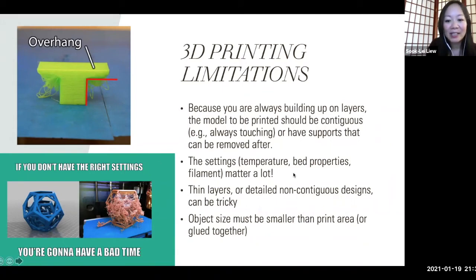And then the settings matter a lot. So we play around a lot of times with the temperature of the extruder, the temperature of the bed, the type of filament, and the slice thickness or the layer thickness, because all of that can matter a lot. So here's a good kind of a meme, but it's also just true. If you don't have the right settings, you're going to have a bad time. So this could be your 3D model, but if you don't have the appropriate settings, this is what you could end up with, which is just like a mess of plastic filament pieces.